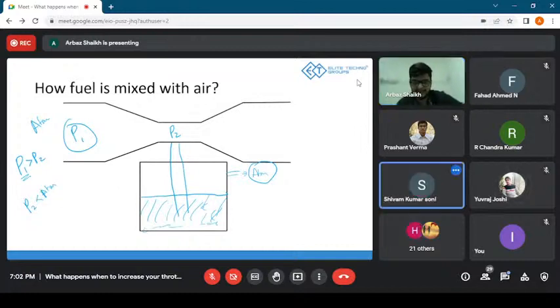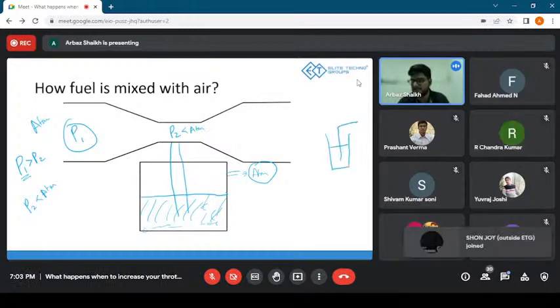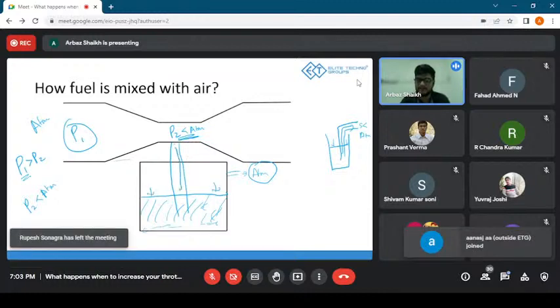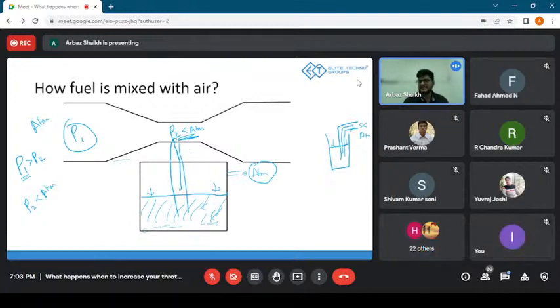Yes, sir. Correct. So now we know this pressure is less than atmospheric, which takes me to the example of our straw. There was liquid in it, there was a straw, there was suction pressure, which was lesser than the atmospheric pressure, and there was atmospheric pressure acting on it, right? And that is why the liquid got sucked up into the straw. Similarly, because the P2 pressure is less than atmosphere, this atmospheric air is going to push the liquid up into the throat. Okay? Is that clear to everybody?